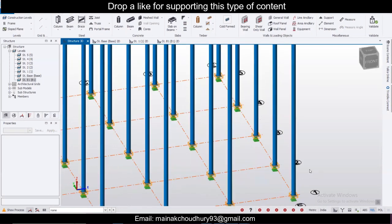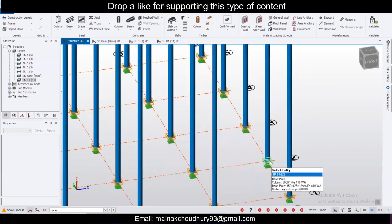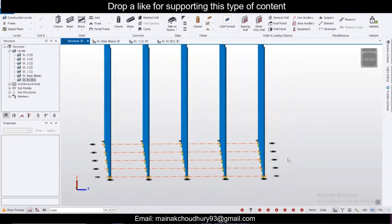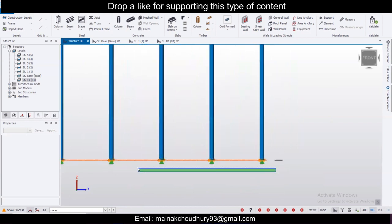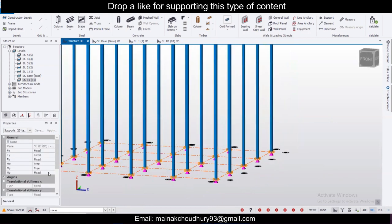You can also zoom in and zoom out like this. You can see that along the base plate this appears. So no problems in that. Now in the 3D view, you can rotate with the help of right click. Hold the right click of the mouse, you can rotate this. Now you can go forward and select all the supports, zooming in and out. So all the supports have been selected.